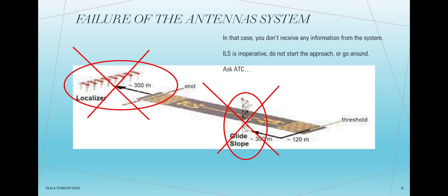In that case, you don't receive any information from the system. ILS is inoperative. Do not start the approach, or go around. Ask ATC.